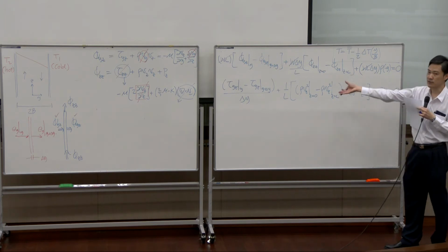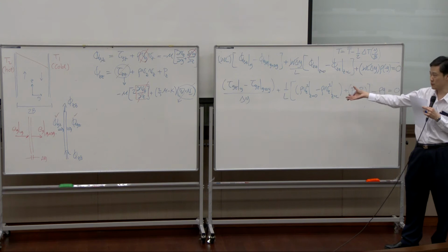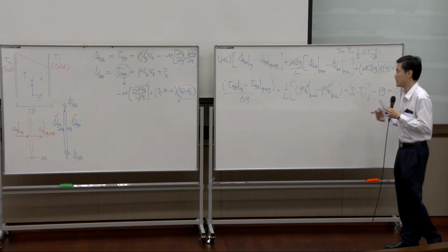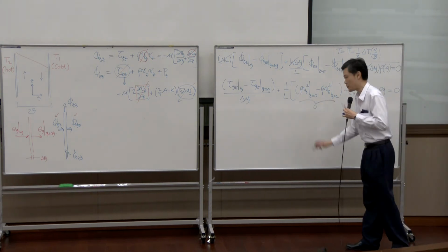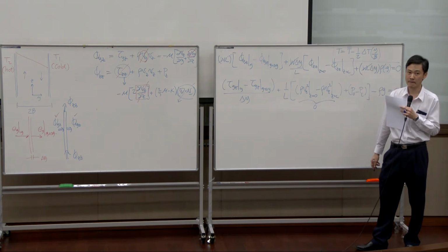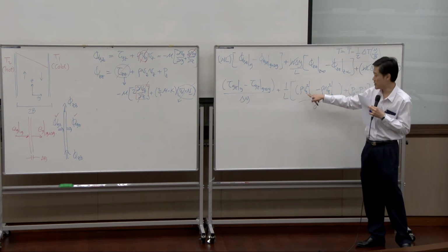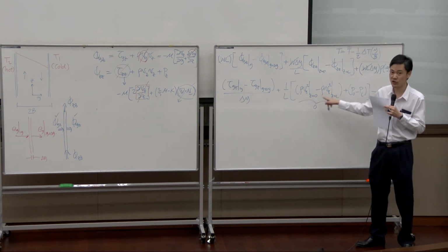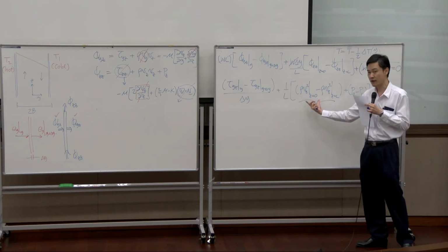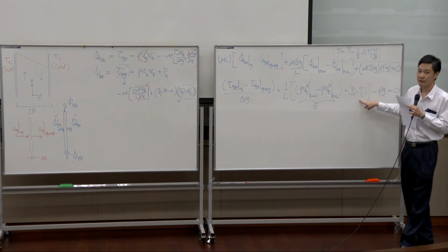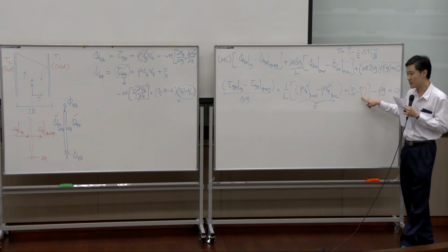Now we have a familiar equation. This equation has been shown to you in the first session of momentum. During that time, we said this term turns to be 0. Why? Because Vz is a function of y. It's not a function of z. So Vz here and Vz there are supposed to be the same. It does not change with respect to z, so they cancel out. Pressure term, can we ignore pressure? Can we drop these two terms? Can we say P0 and PL cancel each other?